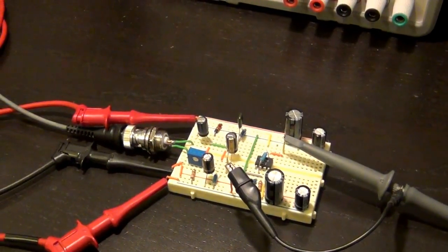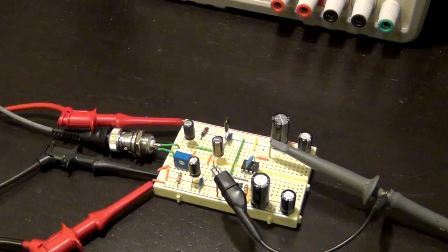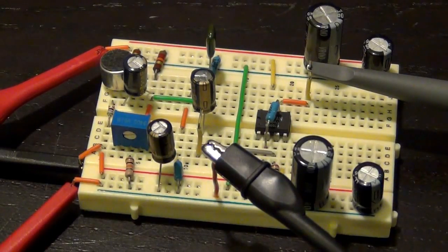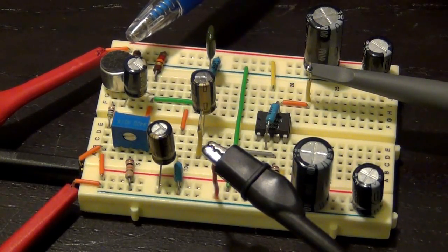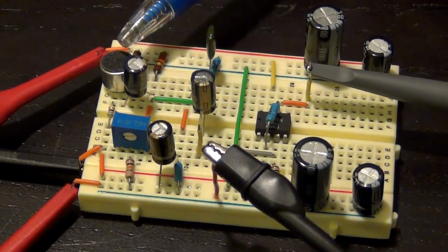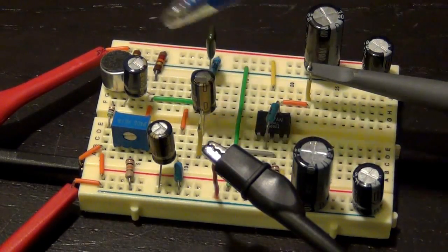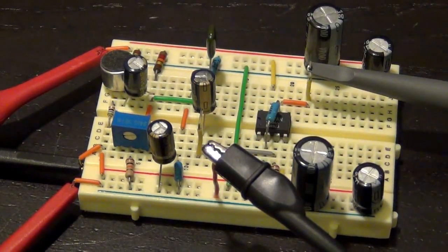Now the only thing to test is whether it can amplify an audio signal. So I'm going to add a microphone to it. All right, I added a simple microphone, and I've biased the microphone from the same power supplies that are used to power the entire amplifier chain, and I have connected the output of our little microphone directly to the bipolar input. So the signal from the microphone goes through the bipolar, through the op-amp, and into the oscilloscope. So I will now show you that.